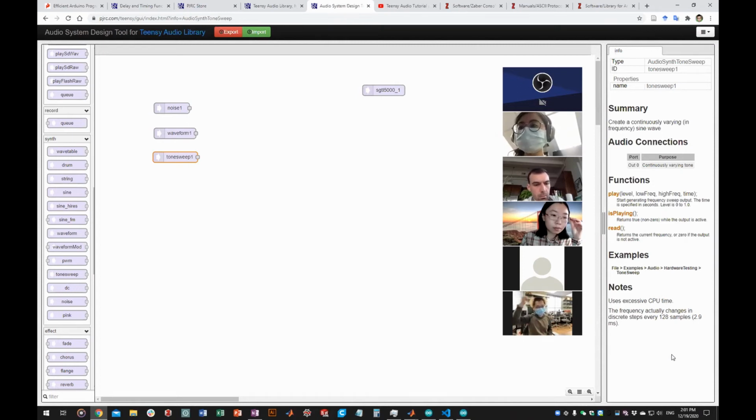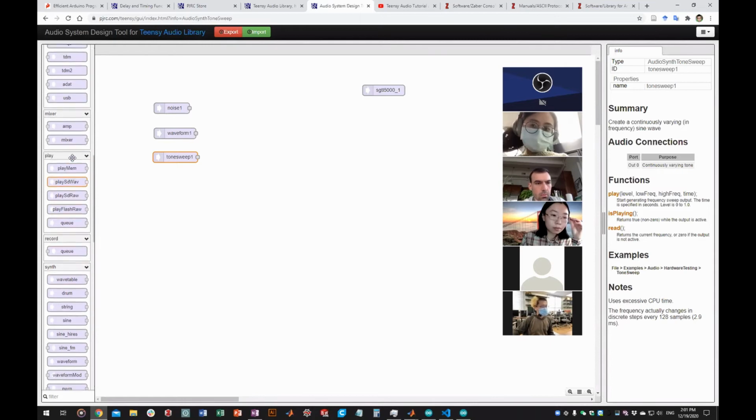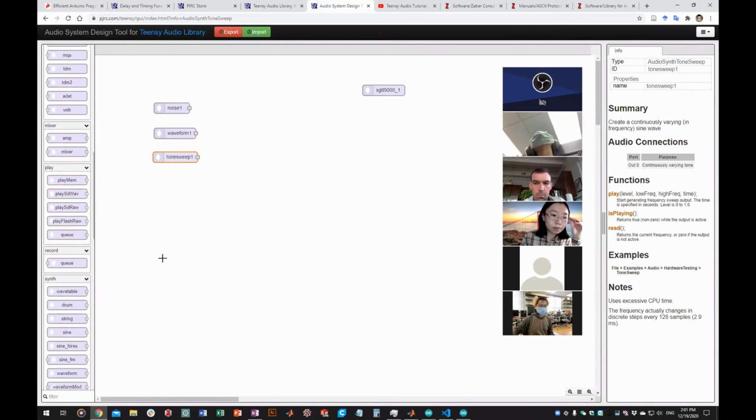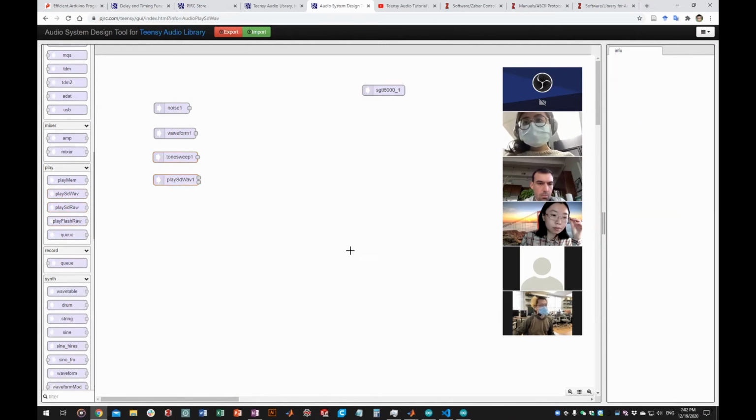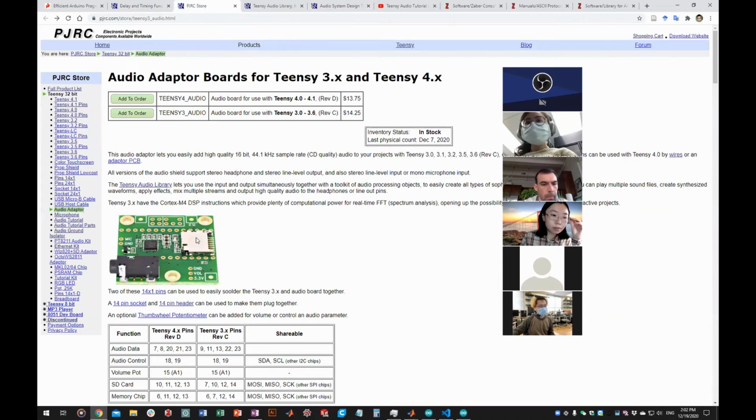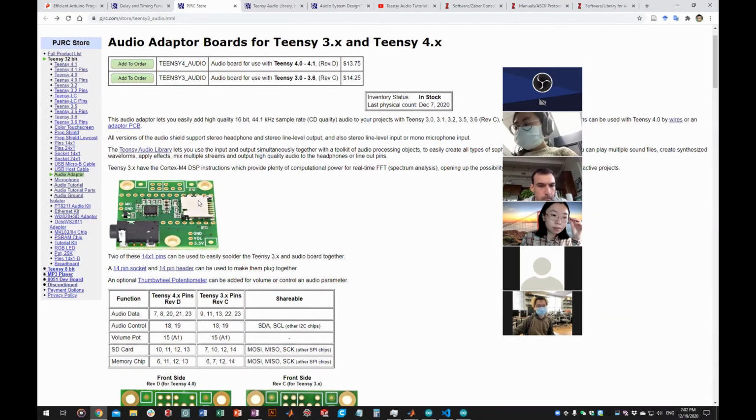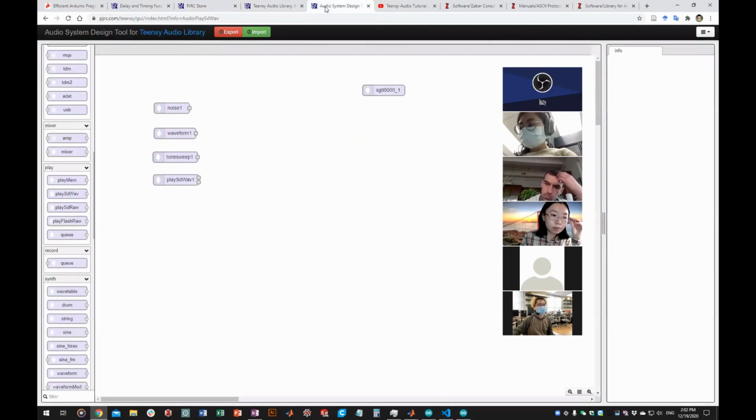At the bottom, we need the capability of playing audio files, right? The module that reads the audio file and generates a sound is over here: play from hardware memory and play from SD card. Here we saved the file onto the SD card and inserted it in. The SD card was inserted in the audio shield rather than on the Arduino board. Although the Teensy 3.6 has an SD socket as well, we need to insert the SD card into the shield.